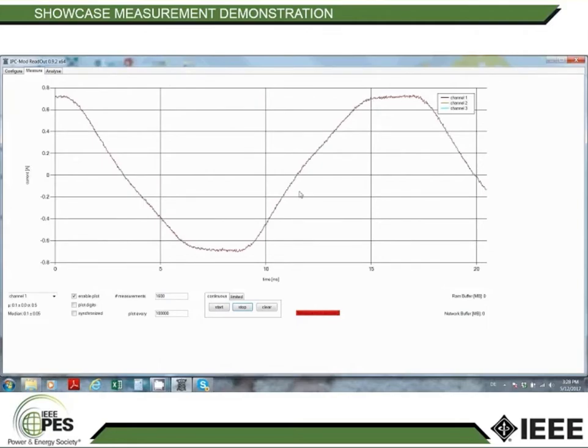You can analyze it. What's interesting then here, we have a plot every 100,000 here, so that means 1600 measurements are actually plotted on the screen, and this is done every 100,000 measurements, means 98,400 measurements are actually discarded. Why that? This is simply for the immense number of data that we get from the module. So we don't want to plot everything here because that would be too much for our PC.